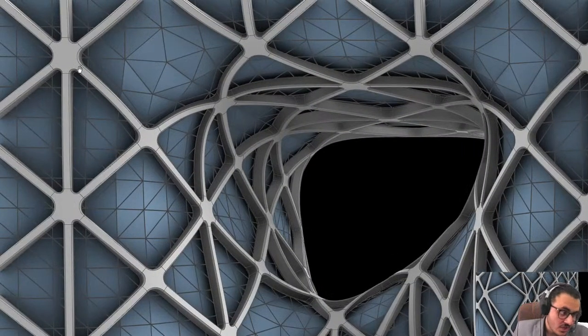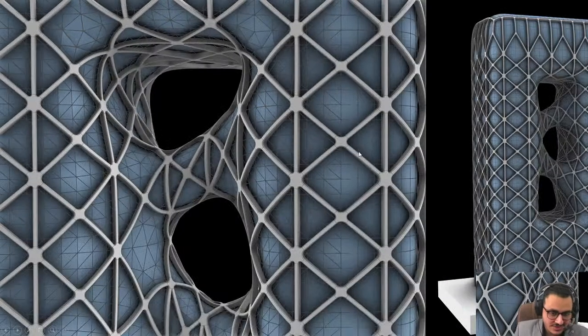There is a chamfer, and there is no such chamfering in Grasshopper, so you need to chamfer it manually, but not manually; you want to chamfer it parametrically. You want to get this nice chamfering feeling and create a simple structure. So you want to create 4 layers. I created 2 layers in the front and 2 layers in the back to create a nice chamfering to the cladding. That's really important to understand.